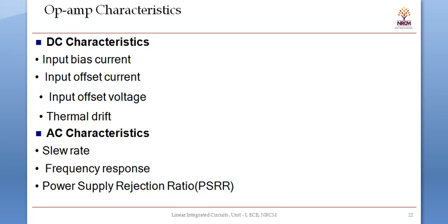Here the slew rate occurs due to the internal capacitance or the external capacitance attached to the op-amp. The capacitor within the op-amp is generally used to prevent oscillation, and this capacitor has the disadvantage that it prevents the output voltage from responding immediately to the fast changing input.